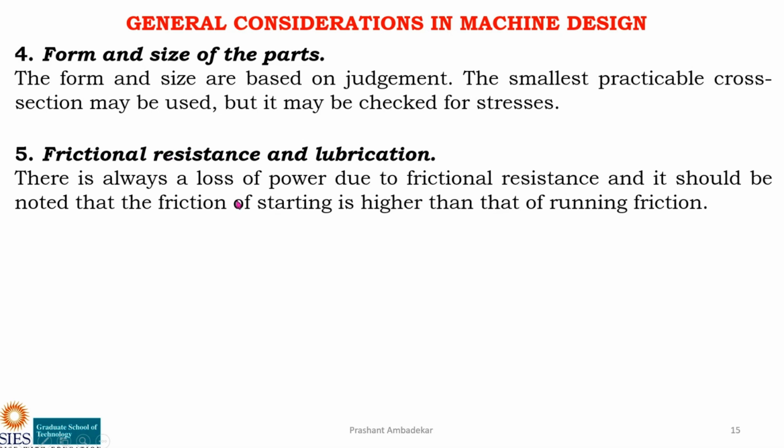Then frictional resistance and lubrication. There is always a loss of power due to frictional resistance, and it should be noted that the starting friction is higher than the running friction. So you have to give some lubrication to the parts where there is high friction. So a proper oil hole should be provided so that lubrication can be given to the parts.